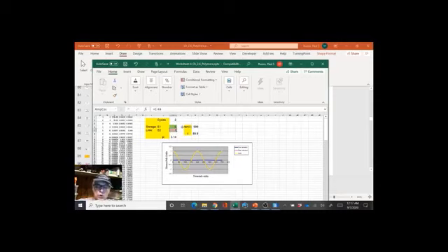And you go to the Newark catalog, or Parts Express, or any of them, or Amazon, and you order some capacitors, and they'll say, what tan delta value do you want? How good a capacitor do you want that to be? Do you want it to store all the electrical energy? If you do, you might expect to pay something for that. Or do you want a cheaper capacitor, save some money, and good enough?